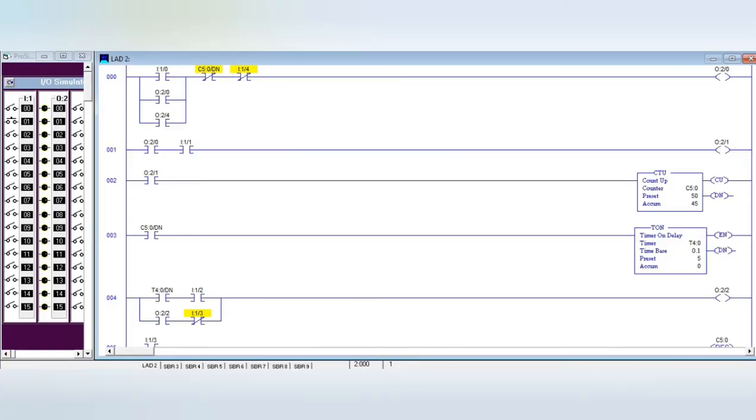I'm going to show you the switches first. This I10 and I14 are the on and off switches for this product. These are the normal switches that you always see in electronic devices. We also have this I11. This is the sensor part: when one can passes through this sensor, this switch is pressed one time, which means one can equals one press of this switch. And we also have this I12 and I13. Both of these control the extension and retraction of the cylinders.